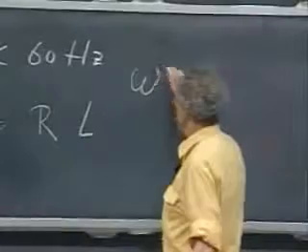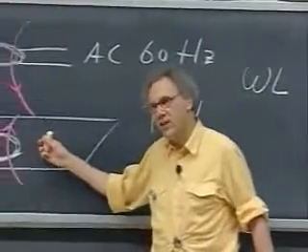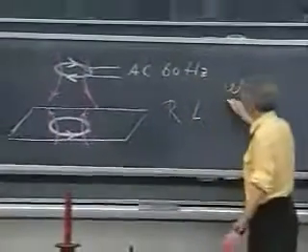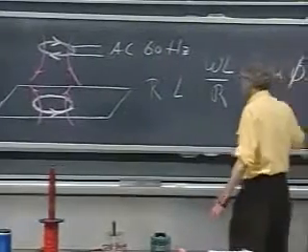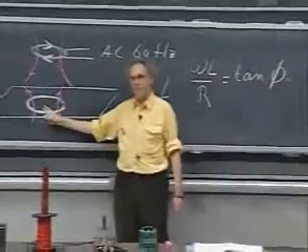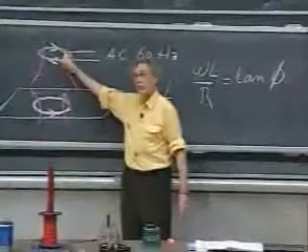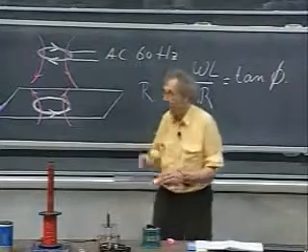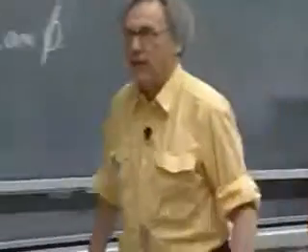And so in this conductor, the induced current here is delayed by a phase angle, given by this equation, is delayed over the induced EMF. The EMF is immediately coupled to what this coil is doing, but the induced current is delayed. And I have something that will allow you to see that perhaps in even more detail.